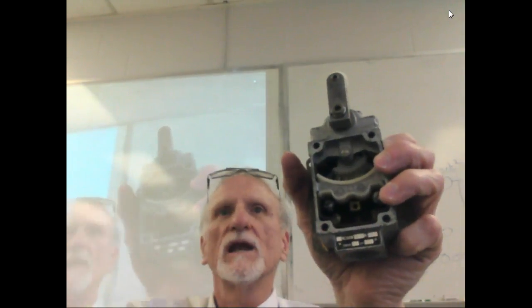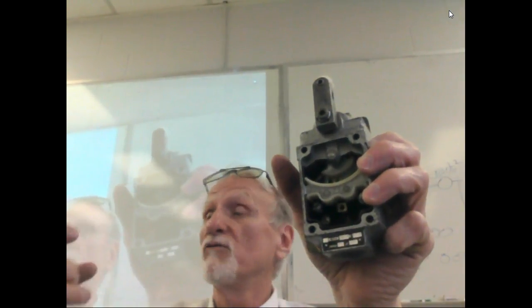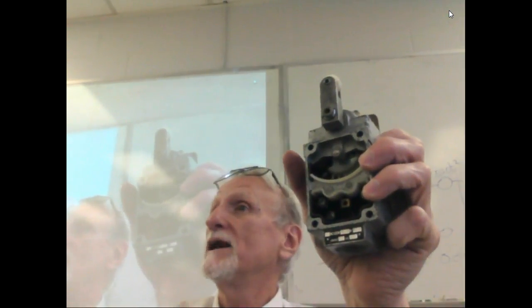These are the actual contacts, you can see in here. It looks like it's got a set of normally open and normally closed contacts. You can actually see the wires where I hooked this up. It got the name because this literally was used to detect limits. So when something hit a limit, it would reverse it or something like that. Now we use them to detect position. We use them to count things. You can get a little small one that's got a big wiper out. These things come flying by and he's just sitting there.